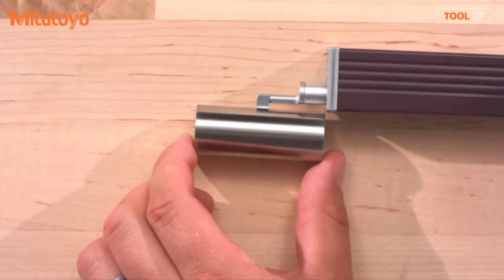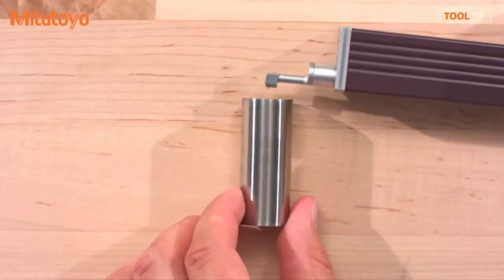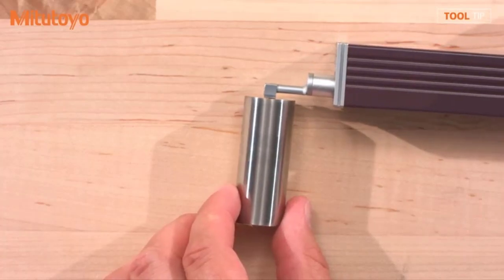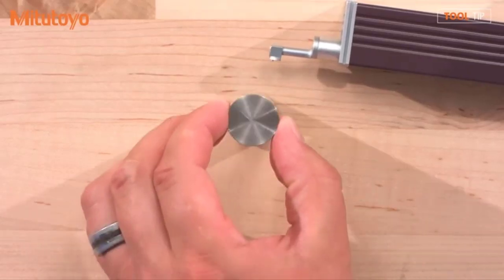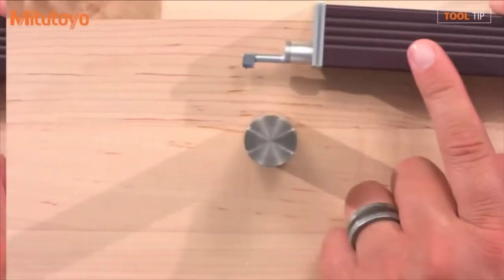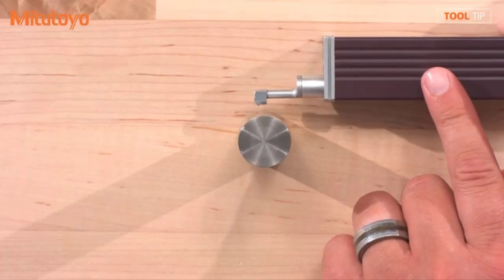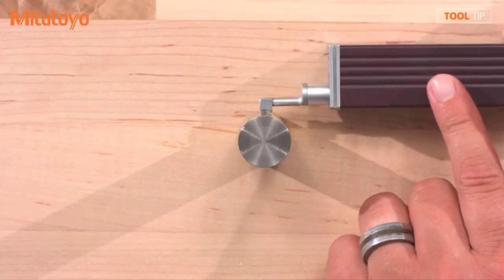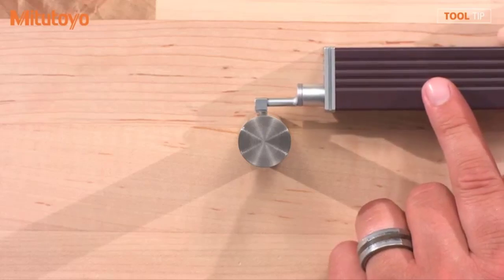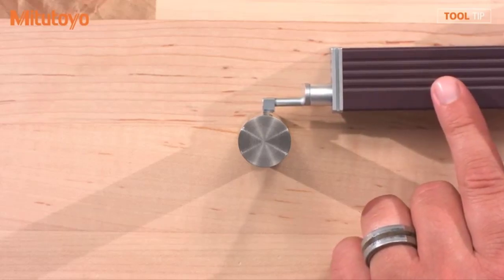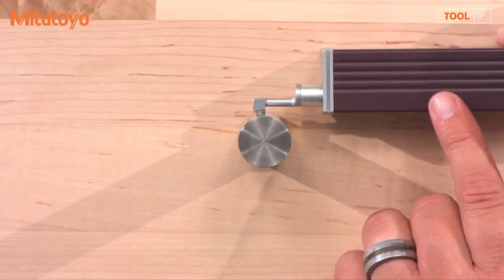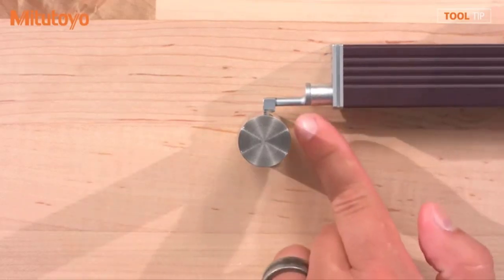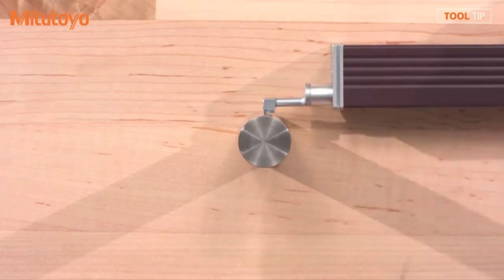That is correct. If you were to measure along the axis of this part, you'd be fine. If you wanted to measure the top face of this part, you'd be fine as well. Now what if I wanted to measure radially? That would be an issue with the skidded system. Let's flip the part up here. If I present the stylus to the area and move it back and forth across the part, you notice that depending on where I am, either the beginning or the end of the skid is going to be off of the surface being measured. I'm going to have a gap at either the beginning or the end of the measurement. Right, and this would be bad because that's the datum and it's not making consistent contact with the part.